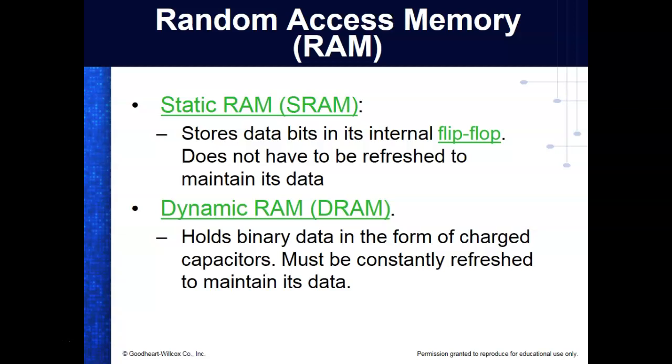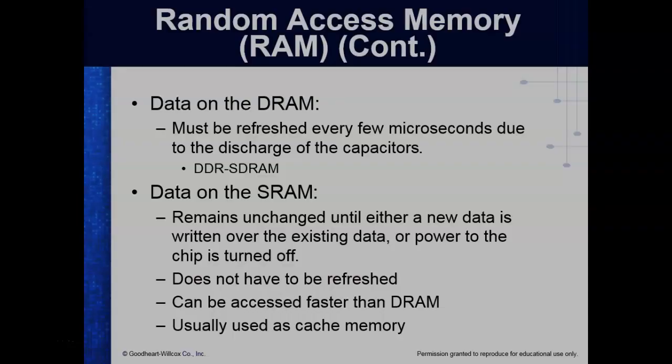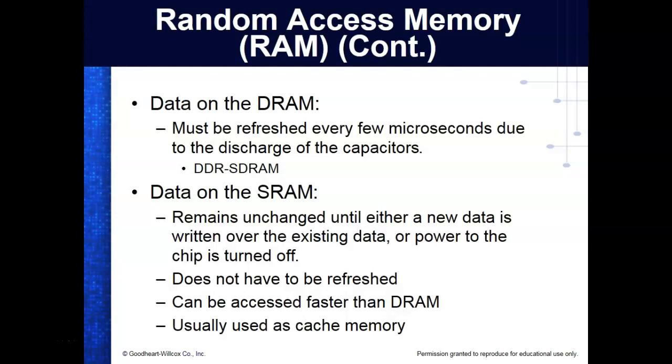Used to, we would do it with a program. All you have to do is just go out and access it. That's all you have to do. And it would restart itself. But since dynamic memory's been around so long, now the support chips actually control the refresh. But the problem is, while it's refreshing, you can't be using it, right? You understand? So DRAM is a lot slower. But now that we have all this cache memory in there, it compensates for it. That makes sense? By the way, memory in computers, we call it DDR. I think we're on DDR4.